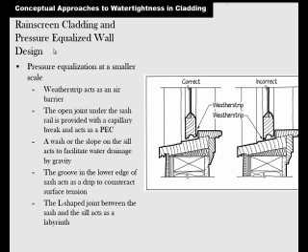So this is also true in our simple home design, or residential, with your window. You have a lot of those same elements. The weather stripping acts as an air barrier, keeping the wind pressure out. There's the weather stripping right there. And if you look on your windows at home, you'll see this stuff or something similar to it. The open joint under the sash rail is provided with a capillary break and acts as a pressure equalization chamber. So that's right here.